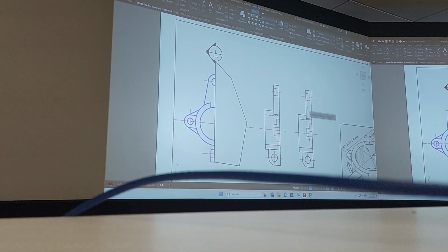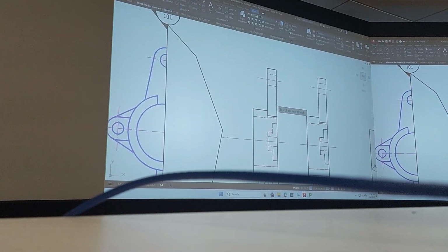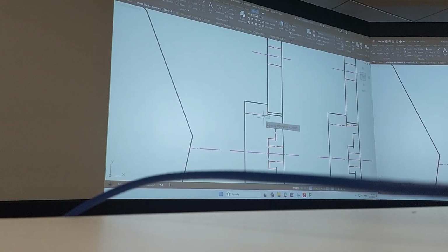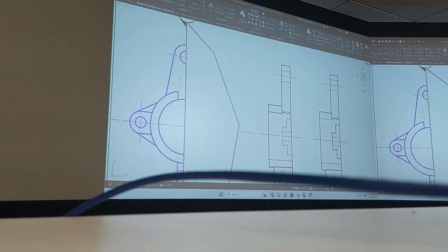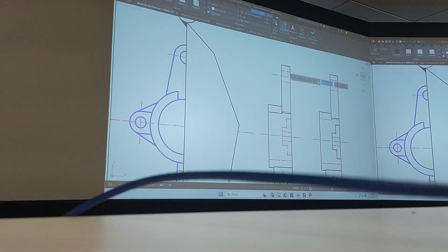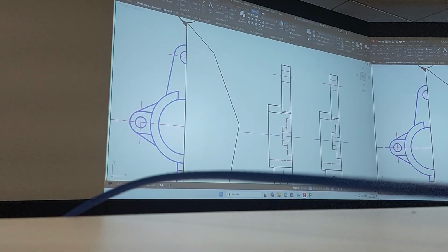I'm going to go match property and turn this one solid, and all of these solid, in fact. And on the other hand, this one here becomes dash, because this is where it hits down here, on the other side, because what's on this side is down the other side. Now I can hatch this all the way, and this one becomes solid as well. So match property, this is solid,